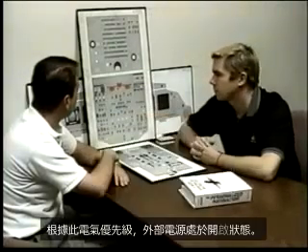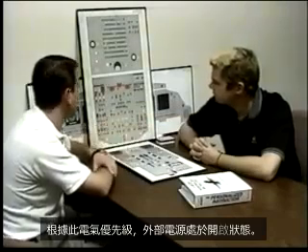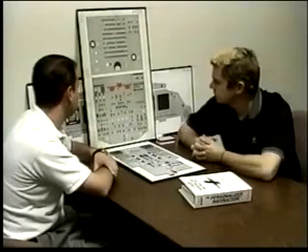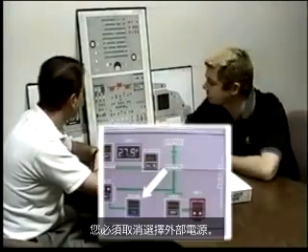Based on that electrical priority, external power is on, you have the APU available. How do you get the APU generator online? You have to deselect external power.